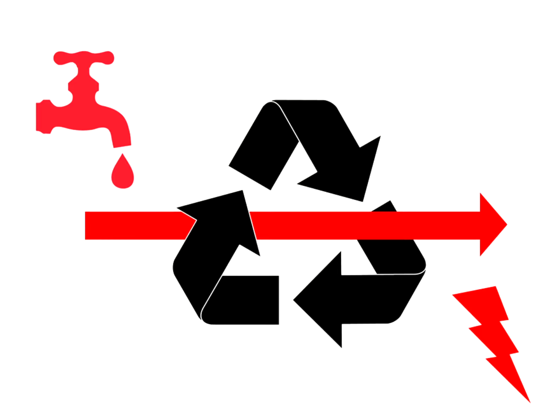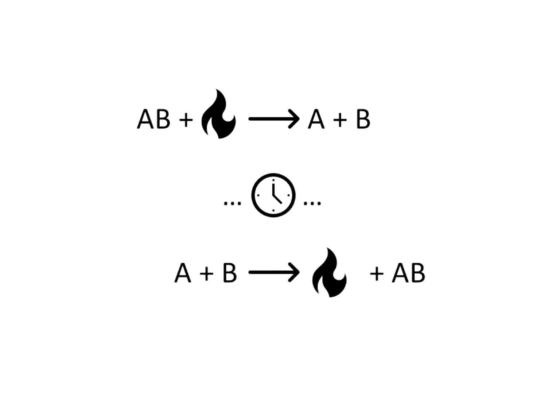The biggest issue we face when we have a stream like this one is the low quality energy it contains. In our case, it is only around 200 degrees Celsius. At temperatures like these, there are limited ways to harness the energy. The way we harness the low-grade heat is via thermochemical energy storage. If we're clever, we can use a reversible exothermic-endothermic reaction.